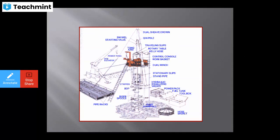So the pump manifold shown here, the riser spools, BOP, stripper, then hydraulic equalizing valves, then power pack, fuel tank, toolbox, hose basket in the bottom, then dual winch, control console, work basket shown there in the top, then traveling slips, rotary table, then Kelly hose is shown clearly, then pipe pole, dual sheave down, then swivel stand, then on the left hand side you see the tong arm, then power tong, elevator, etc. Stripper, then BOP riser spools.